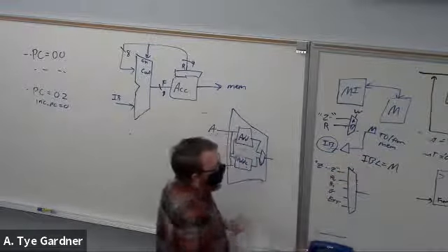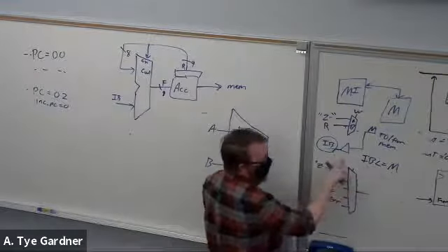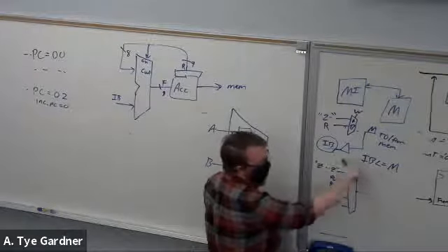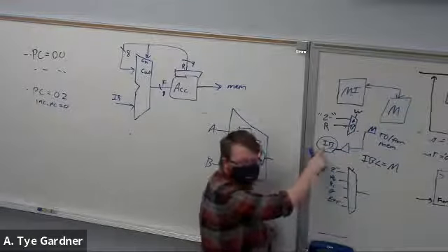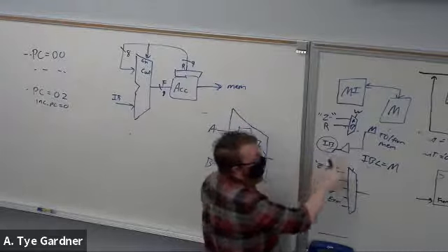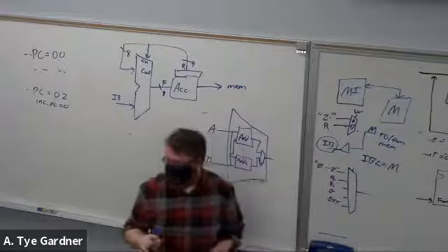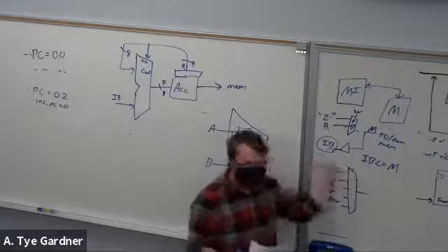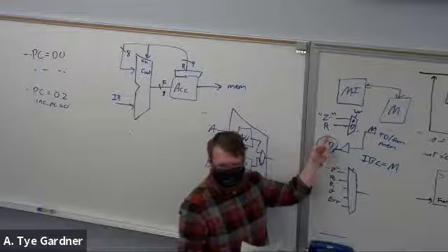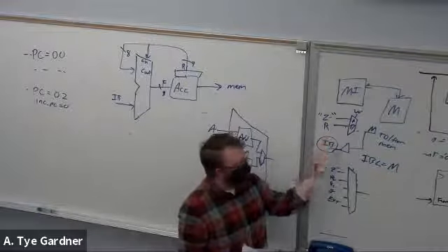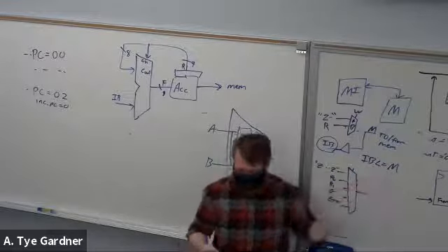Okay, so what that will do is this signal, IB and M are the same, but it's allowing us to create a port for IB, which is just an output, and a port for M, which is an in-out, right? It's turning an in-out to just an out, because this may be tied to R instead. That's why we want this buffer here. That's all it takes, is that outside of a process.